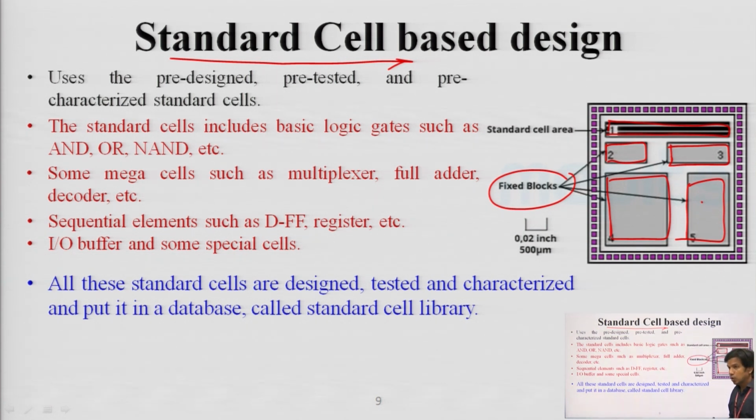If you have done some circuit analysis in Cadence Virtuoso, then you can see that before designing any circuit you create a library, and in that library we have different pre-designed components. That is already pre-designed and pre-tested, but you can also modify it based on your optimization technique, which is also allowed. But these are the standard cells. You can see it here.